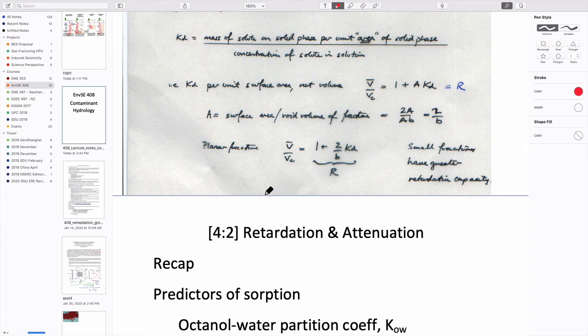And then we can use that to redefine our coefficients: dispersion divided through by retardation, and advective velocity divided through by the retardation coefficient. R is just a non-dimensional term that reduces each of those parameters, and we can use all of the tools that we've used so far to predict how far it goes downstream, when it will arrive at some compliance point, and how much the concentration will change within the aquifer as a result, just by using those very simple concepts.